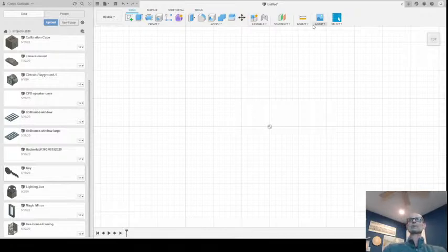The DXF. Okay, so we can insert. We can use the insert tool, which is part of the design tool set over here on the end of the bar. You can insert a DXF. You tell it what plane you want to insert it onto. So that's the flat plane looking down upon this. And so I click that.